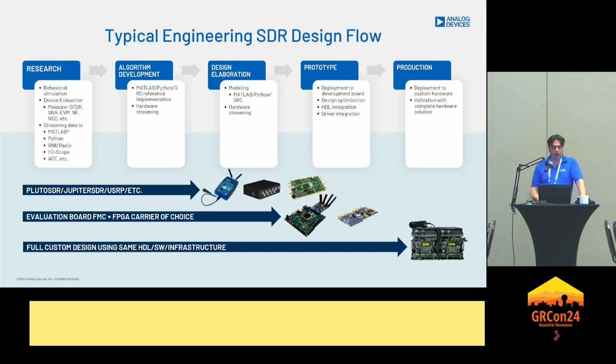So we all kind of know this. You can use commercial off-the-shelf SDR modules until a certain point. You could even ship a USRP or something like that in a product, but many people go beyond that point and they create full custom hardware, and that often involves FPGAs. So it's kind of the last prototype production step. Also, some customers I've seen actually skip the commercial off-the-shelf SDR phase and directly move to an FPGA carrier board with some FMC add-on hardware.